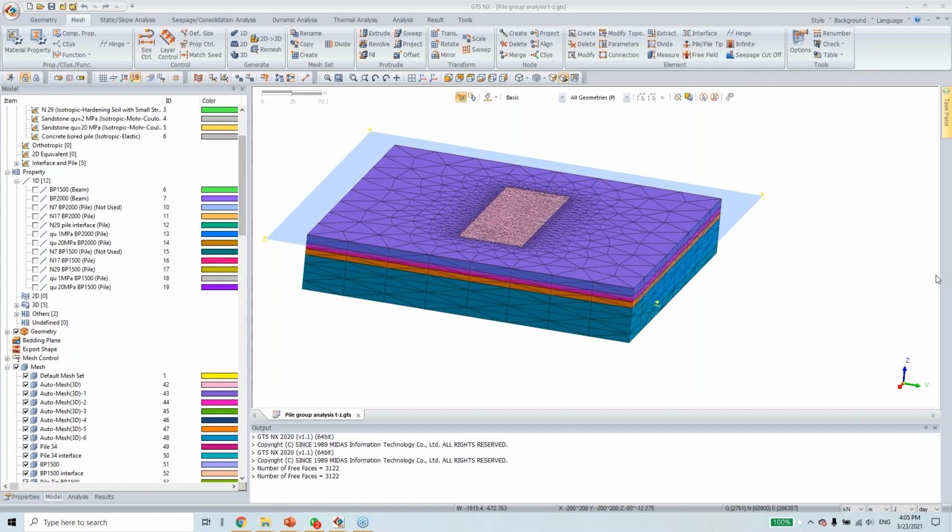Okay. There's a question from Lo Ying. She asked, for the BB Plaza excavations, how did you define the water table levels within the excavations, MRT tunnels, neighboring basement? For fully coupled effective stress analysis, what is the reasonable tolerable error?